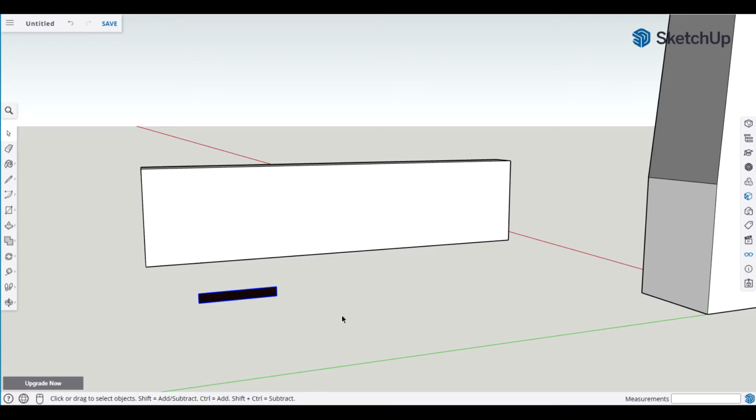Now I'm going to move this, and we want to create 2 in the center, so we're going to evenly distribute it. We're going to distribute 4 evenly, and then we're going to delete 2 of them out. So let's hit M, click the corner, snap it to this corner, click again, start to bring up, control key to copy, bring it all the way to the top.